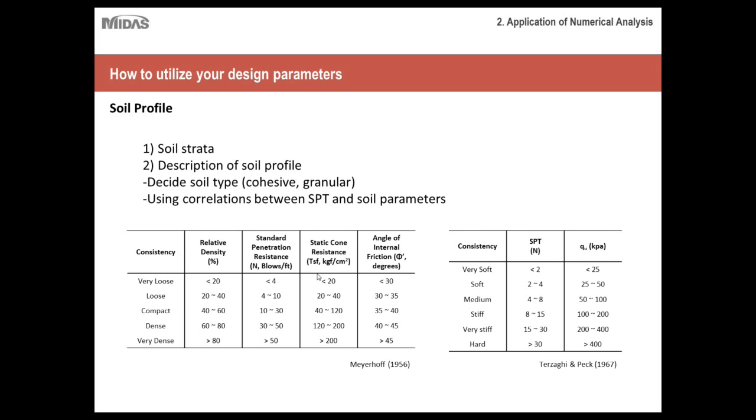Okay, so soil profiles. I'm sure you all are familiar with these types of soil behaviors and characteristics. For example, is it cohesive, is it granular? Also you would need your SPT N values, your consistencies, your angle of internal friction, which is especially important for foundation type projects or pile foundation projects, etc. So it's very important to have all of your data at hand and ready before you run your numerical model.